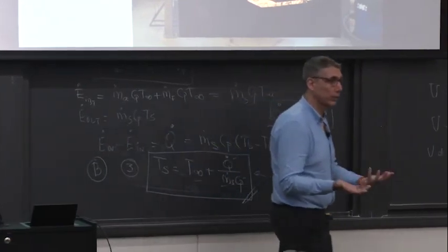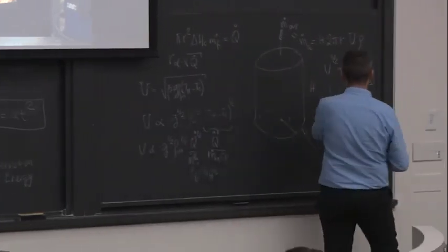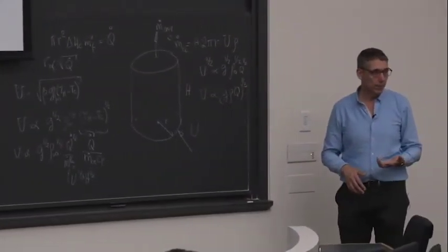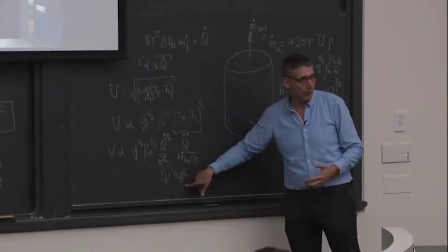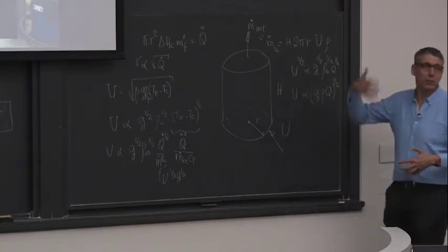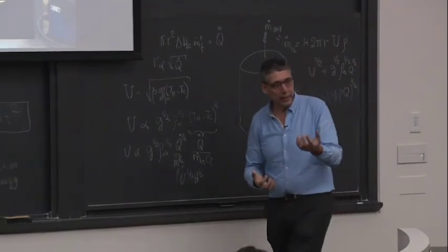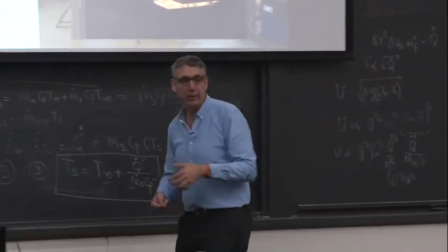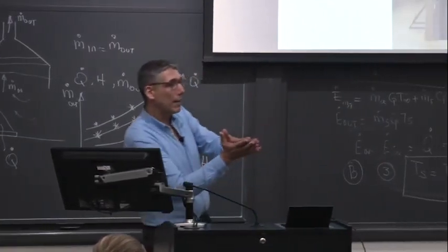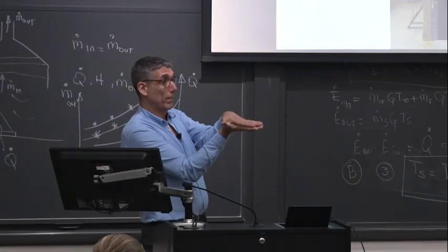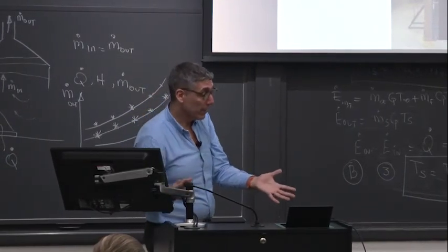And the only point I wanted to make is that once I do all the simple mathematics, effectively everything comes out to the power 1/3. Okay, and if I repeat the same analysis, but now I use the h, the h will come to the power 5/2. Is that okay? So basically your mass of air entrained is proportional to q to the 1/3 and h to the 5/2, okay? So if I scale it down, then all the data collapses into a constant number. Okay, and that number happens to be 0.2. Is that okay?